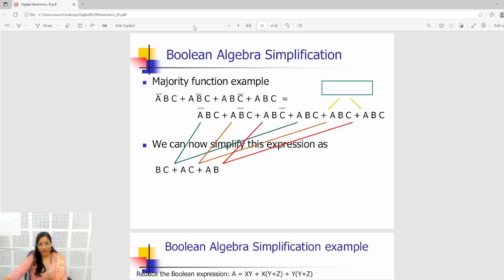Here we are considering an example as a question. How do we simplify it? You can see these colored arrows: the first one is green, then orange, and the red one. In green we are combining these terms wherein we get a common term. So here common terms are b plus c. In bracket we get a plus a bar, and we saw in the Boolean identities that a plus a bar is 1. So we get the simplified term for the green ones as bc.